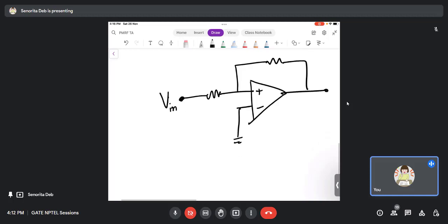Remember, all other configurations that the Opamp has, as a buffer or as an inverting amplifier, all these are negative feedback configurations. Positive feedback is used whenever you want to do either a comparison, a regeneration, or an oscillation.